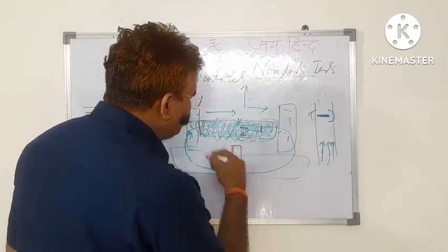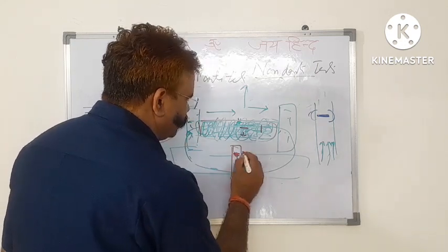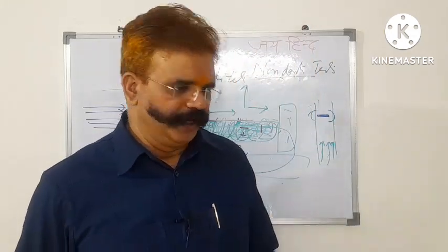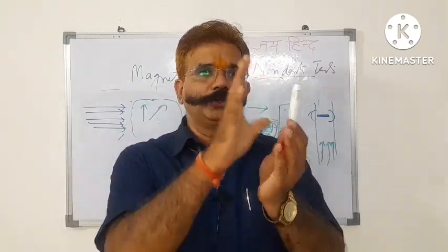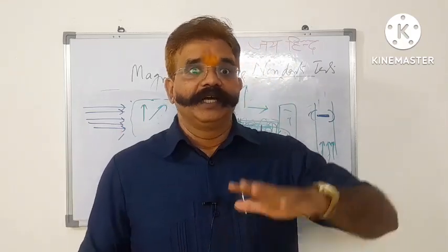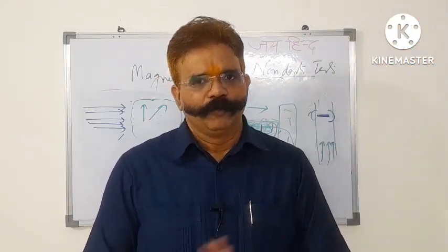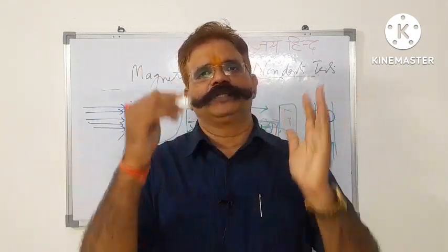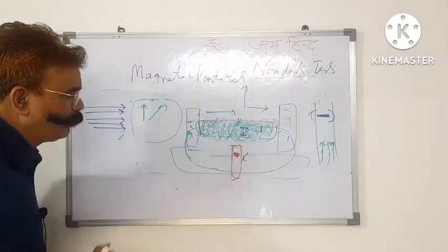In that direction, these magnetic lines of force will be perpendicular to this cross section, this crack, and then that crack will be checked. So in this field, any item is tested in two mutually perpendicular directions, so that if any discontinuity went unnoticed, being parallel to the magnetic lines of force, it will be detected in the other cross section once the magnetic lines of force are crossing that particular discontinuity. So you have to keep this in mind.